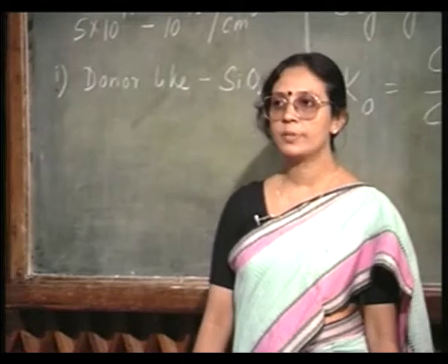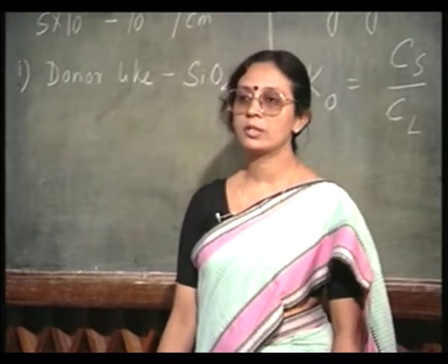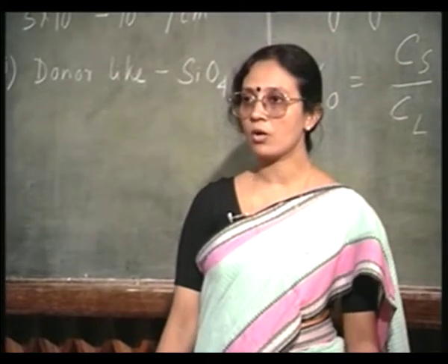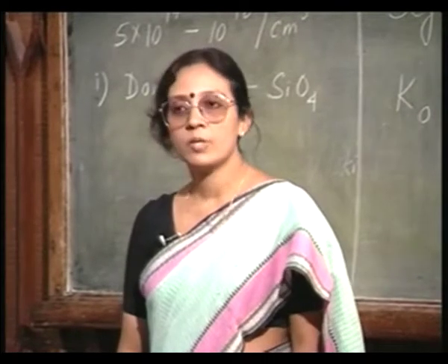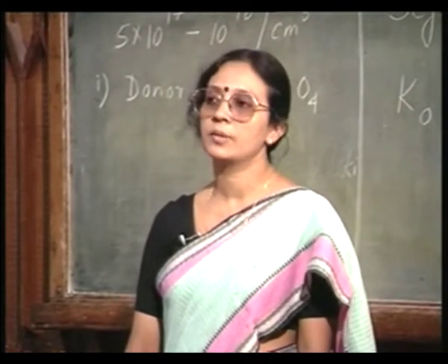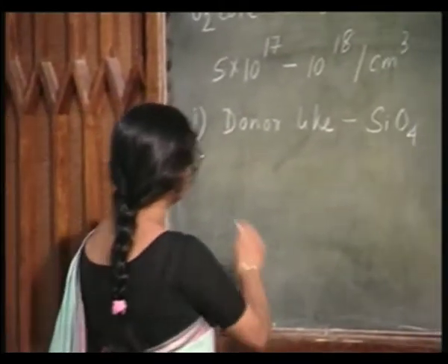This complex will be electronically active, therefore, it will affect the resistivity of the grown crystal, and the formation temperature of these complexes is around 450 to 500 degree centigrade.